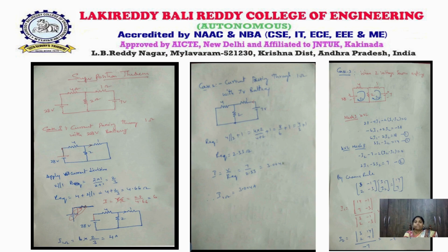Accordingly we have to solve this circuit so that we get the resultant, or the algebraic sum of the voltages or currents, or the response through a particular branch, by considering individual sources acting alone and the remaining sources replaced with their internal resistance.